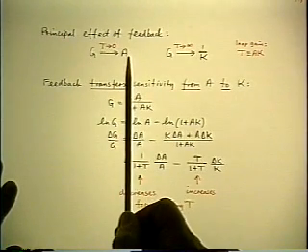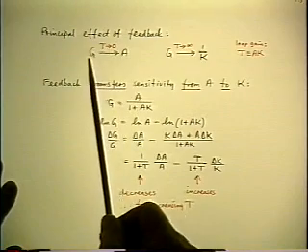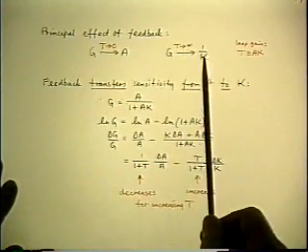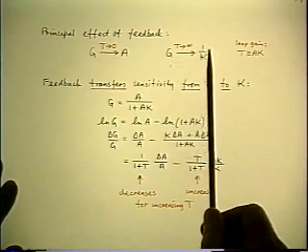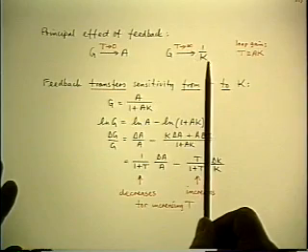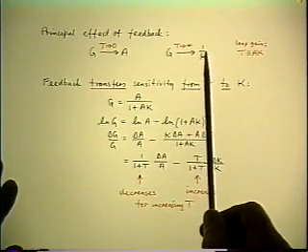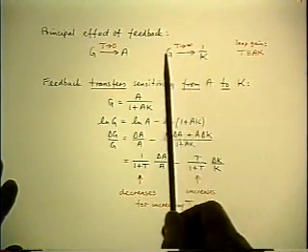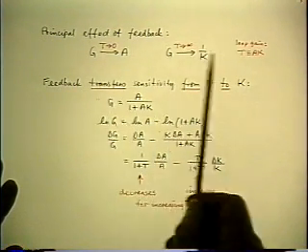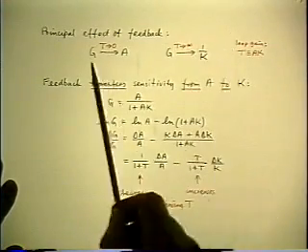So any variation of the A parameter shows up 100% in G. If you go to the other extreme, G approaches G infinity, which is 1 over K, when T goes to infinity. So variations in K show up 100% in G. That's complete transfer from one extreme to the other.